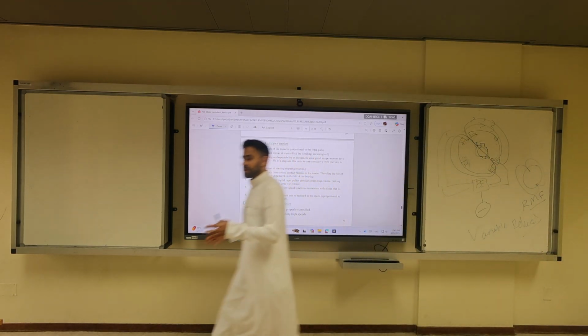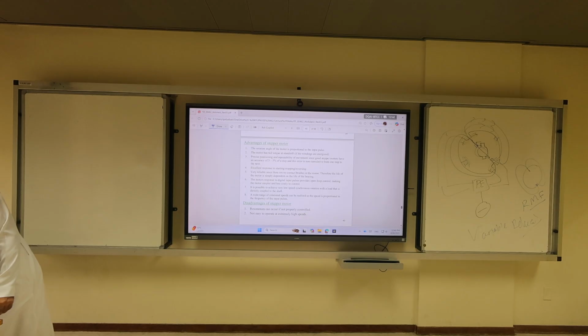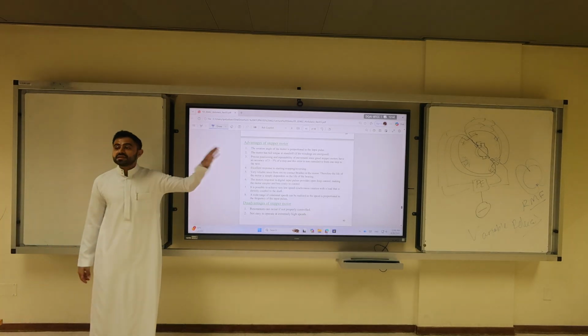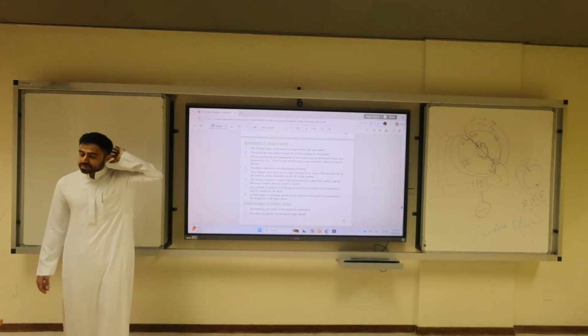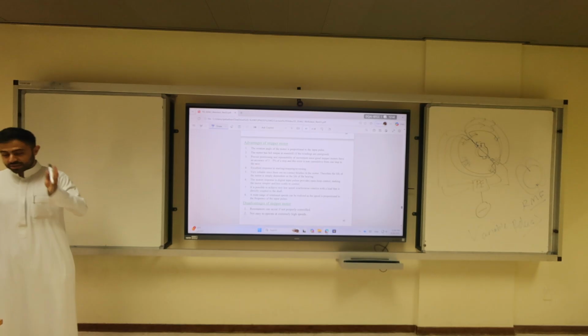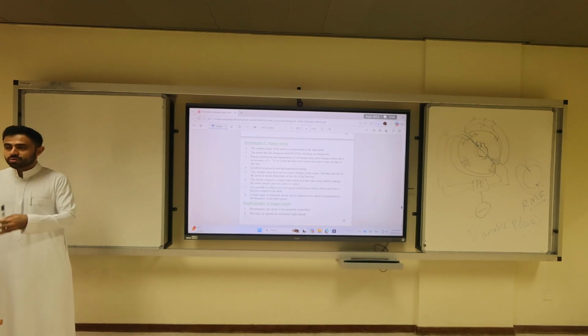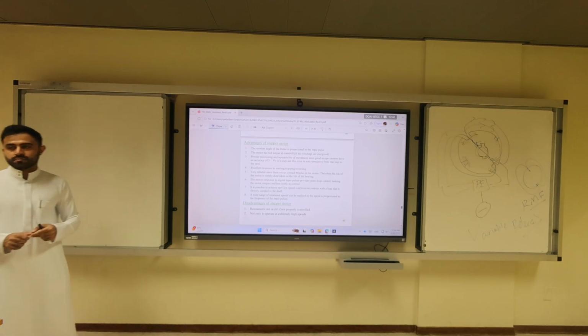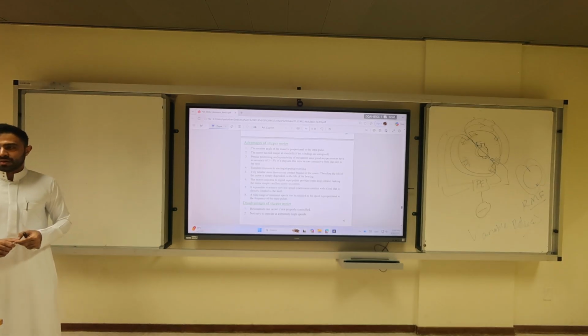This is the simplest stepper motor type, which is called the variable reluctance. This is in a nutshell how a stepper motor works. No magnets, no AC, it's just DC with some power electronics to control the transistors. You choose the angle depending on the number of coils. That is not coils, depending on the number of salient poles. Doctor, the range of speed is limited here.